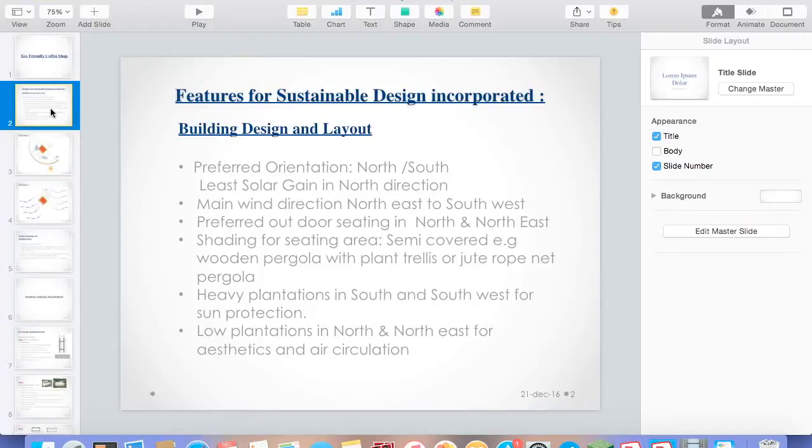that we have more openings where the least amount of sun rays are received. So we would place it in a way that we have more windows towards east and north, and the least windows on south and west. Reason being, our sun direction path is from east to west via south, and the west is the place where sun is at a lower altitude and is very strong.